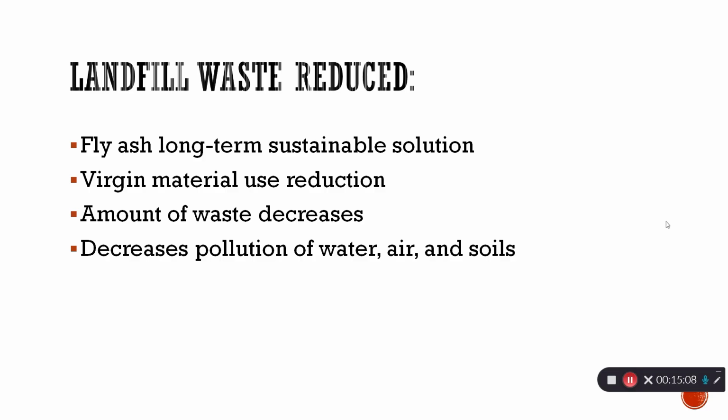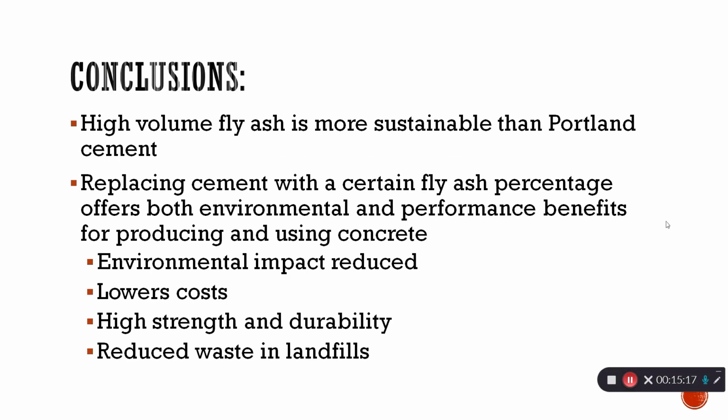We can think of the replacement of 1 ton of fly ash in a mixture as meaning that 1 ton of cement will be displaced, and the amount of waste going to a landfill is reduced because of the fly ash being used. So, conclusions of this review: the reviewing of high volume fly ash as a sustainable alternative to cement used in concrete mixtures shows that fly ash is indeed a more sustainable option to use in a concrete mixture than Portland cement. Ultimately, replacing cement with fly ash to a certain percentage in the concrete mixture will offer both environmental and performance benefits for producing and using concrete.